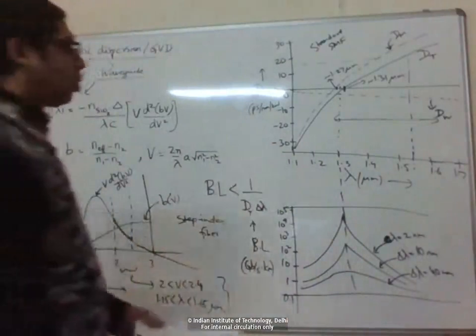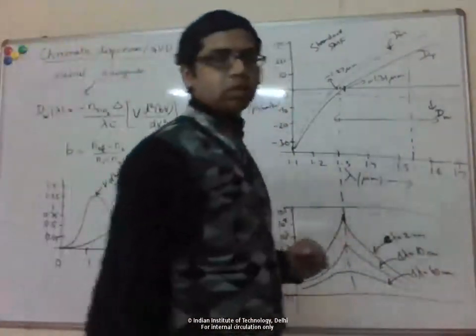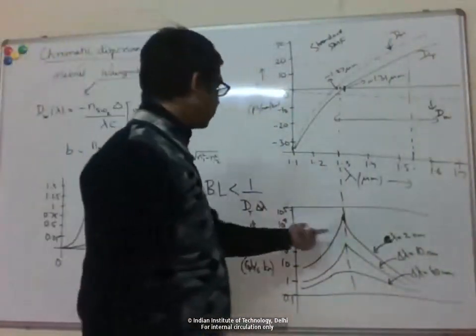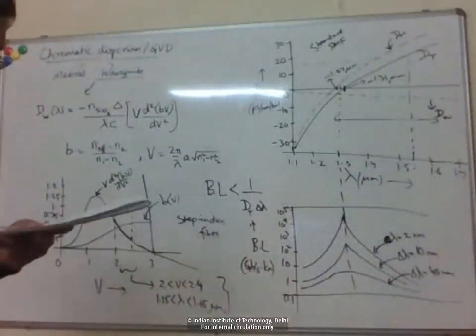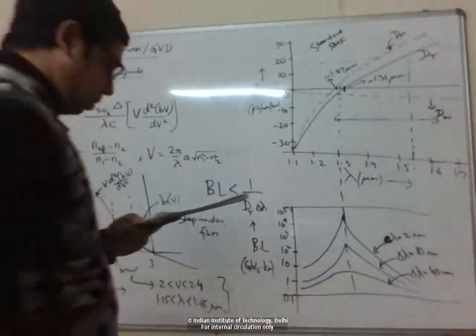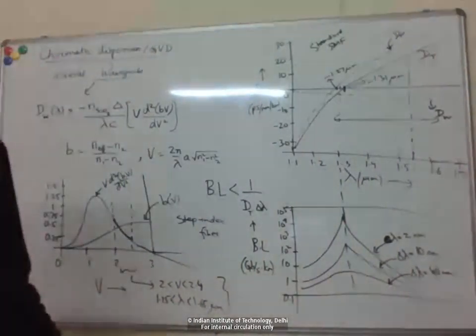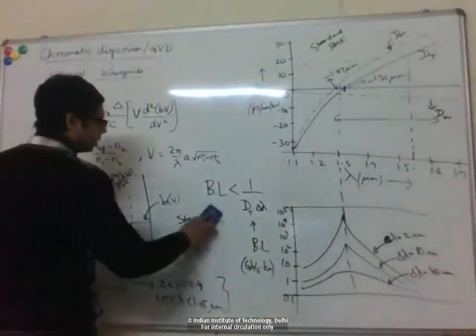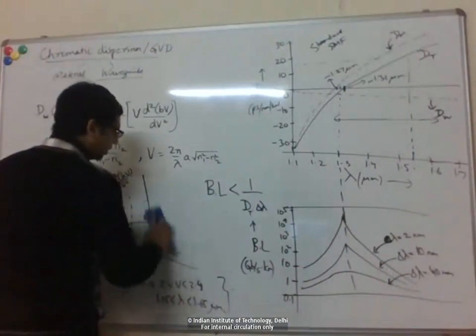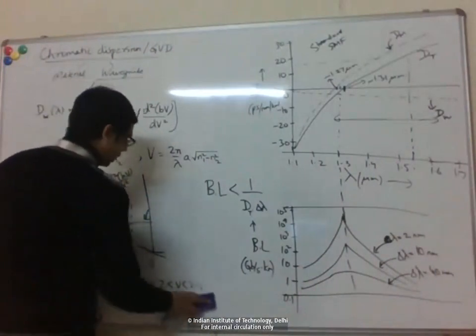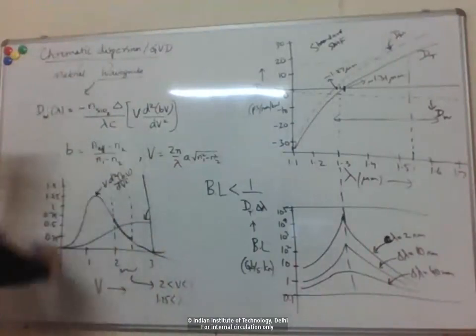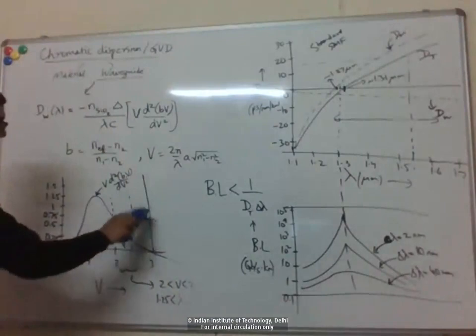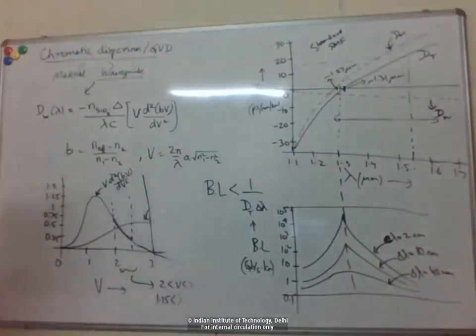For long haul links, we would want to use this wavelength because of the lower loss, but you can see that dispersion limits. One way to tackle this is using what are known as dispersion shifted fibers. This waveguide dispersion depends on the fiber parameters, on this BV curve, which we get from solving the modes.